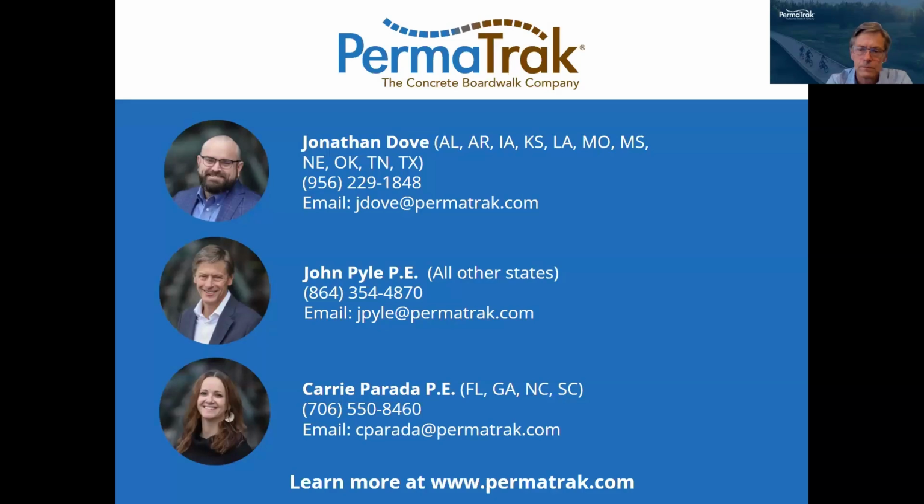And I talked briefly about the basis of design and the performance specification, so you have to go through those steps that we talked about. Decide where you want the boardwalk, decide how wide the boardwalk is, decide on the alignment of the boardwalk, set the physical parameters, and then evaluate the material by looking at those 4 components that you have to evaluate when you're determining a boardwalk cost, because of course cost is going to matter.